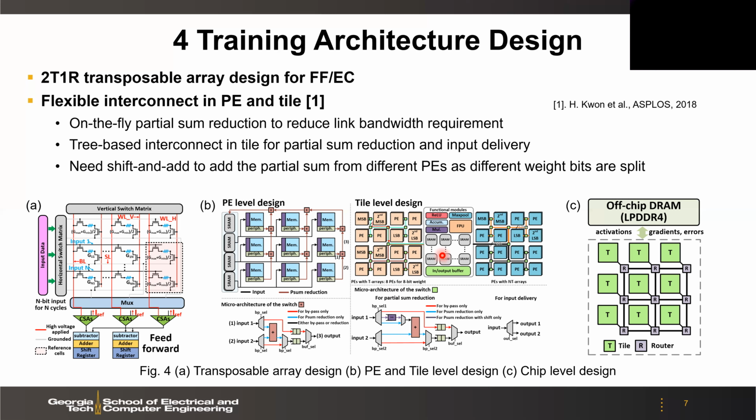In each tile, we have a 512 kilobyte SRAM input buffer to store the input or output data, such as the partial sum, activation, error, and gradient.